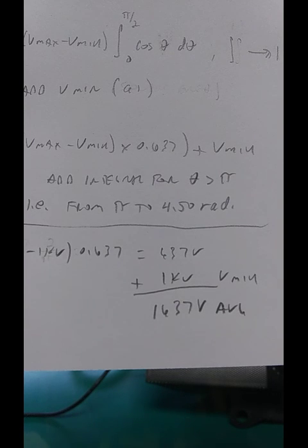This is confusing and misleading because we tend to think of power by Ohm's law, volts times amps. Well, that's a very high voltage. It ought to be a high power. It would be, except that operating up there close to cutoff means a very low current. So we can't judge power output just by looking at plate voltage.